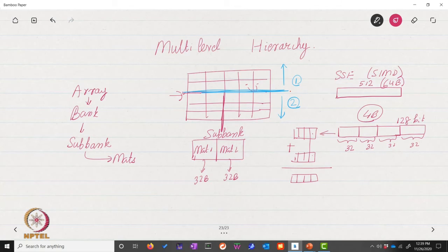Alright. And so basically from an electronics point of view, when you read the Elmore delay model, you will realize that the latency of a wire, like a word line or a bit line, is proportional to the square of the length of the wire. So we typically don't want long word lines and bit lines. That is why we would like to have small arrays, where small arrays can provide a part of the data and we can merge it. Alright, sounds good. So we then, unfortunately, mats are further divided into subarrays.